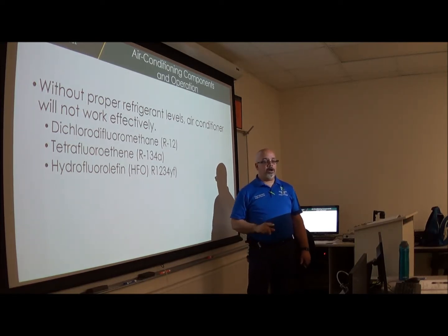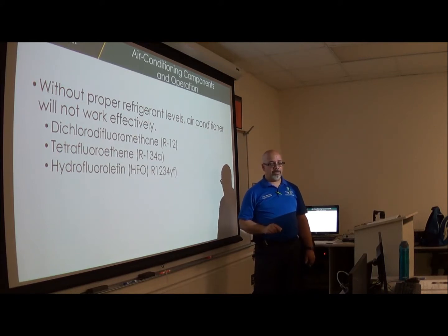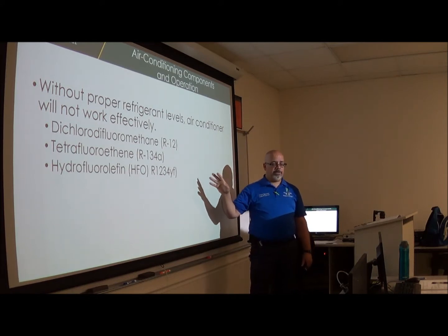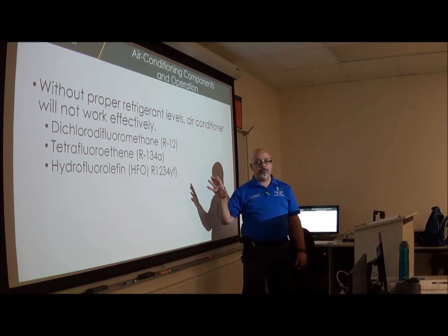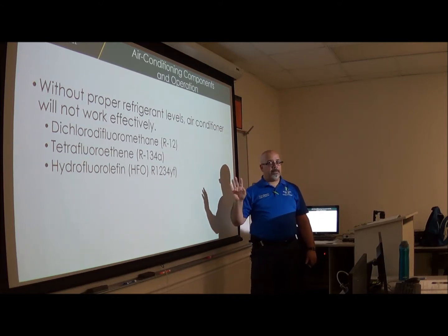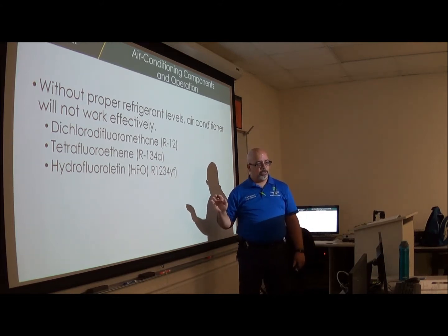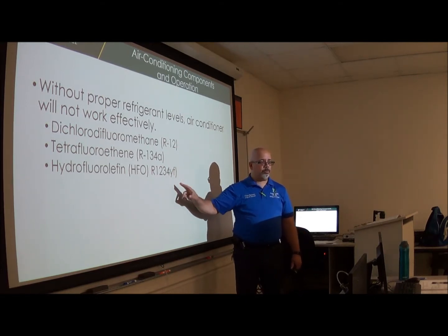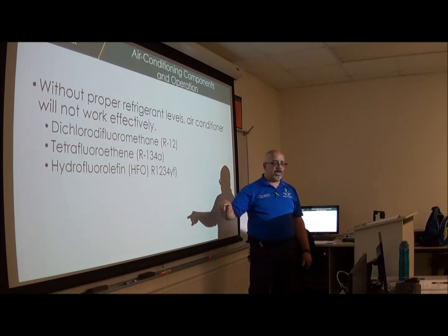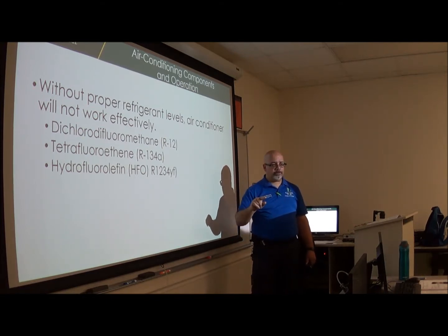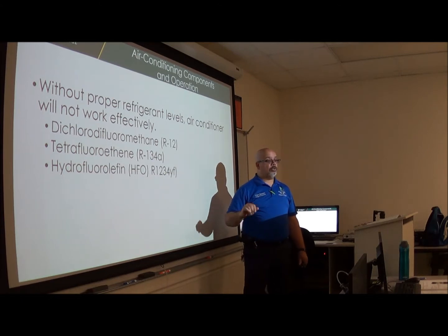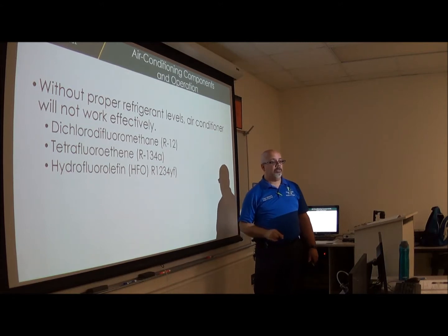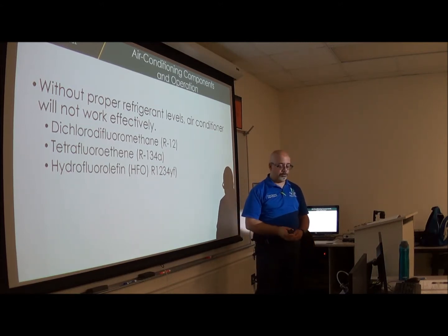Right now, not all the manufacturers are using it yet, but by law, for every brand, it's going to be officially 2022, when they cannot make any cars with 134A anymore. It has to be 1234. But there's an exception for light duty trucks, which is 2021. So after 2021, every light duty truck has to have 1234. All the others would be for 2022.